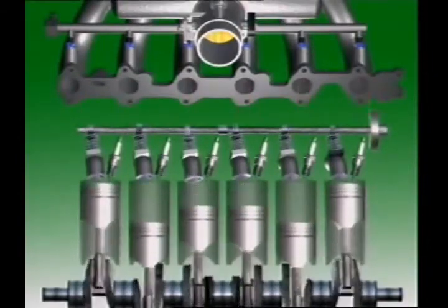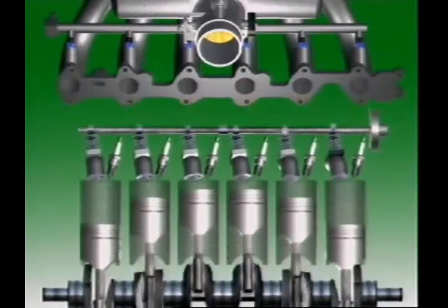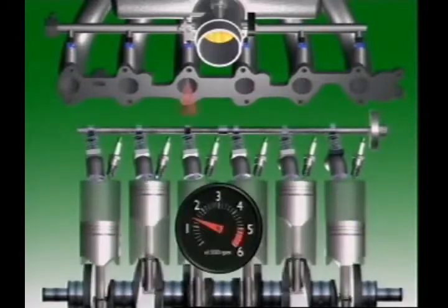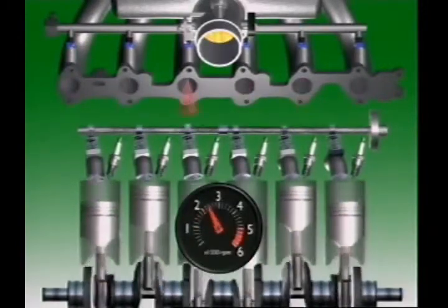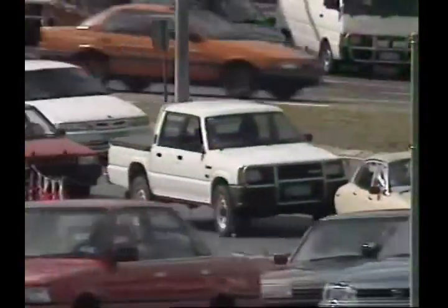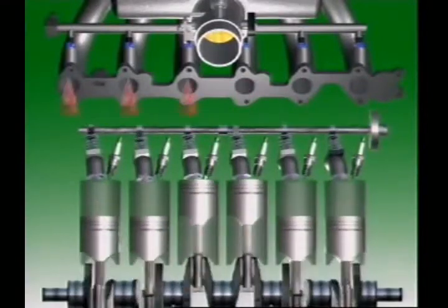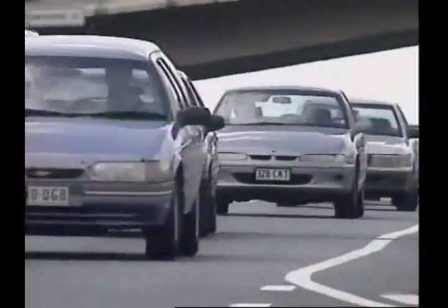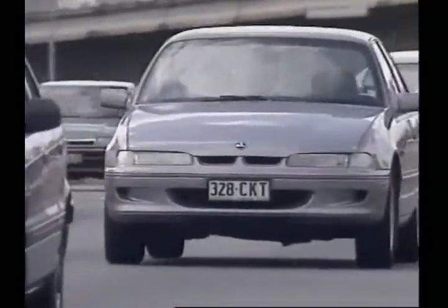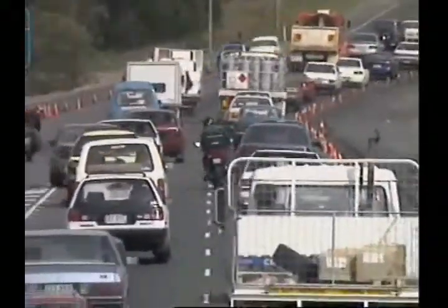In some applications, different modes of injection are combined so that the mode changes according to the operating conditions. Sequential mode may be used for low engine speeds, changing to simultaneous mode at high speeds. The same principle is used in changing from light loads to heavy loads. Similarly, the mode may change from group injection to simultaneous. Using different modes for different operating conditions makes the most of how the fuel is used, and that improves power output, fuel economy and emission control.